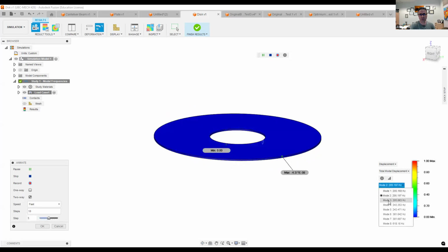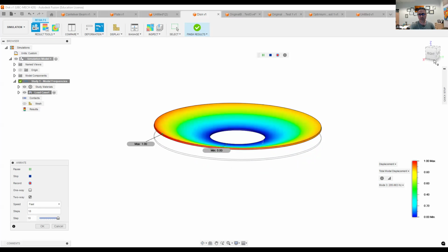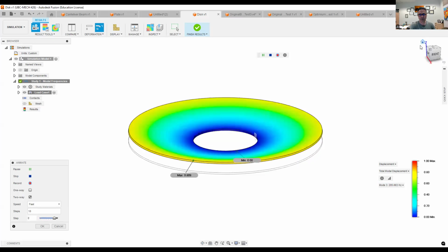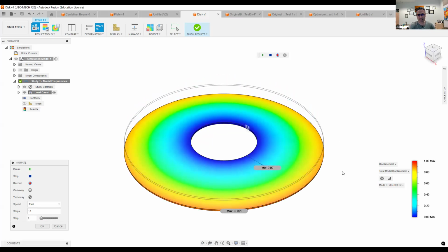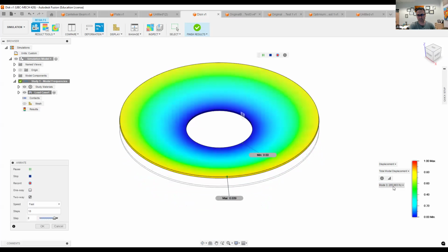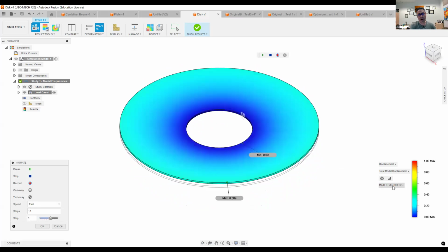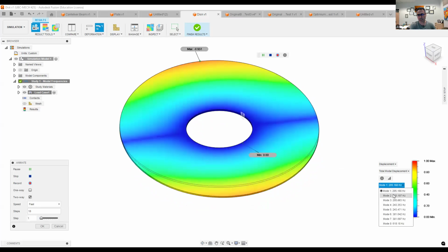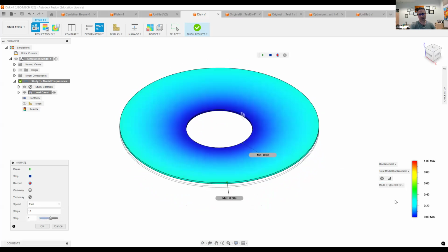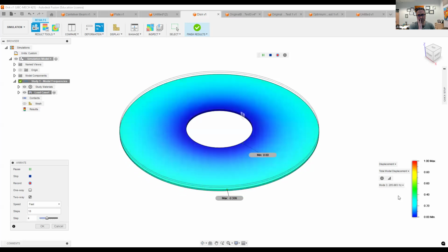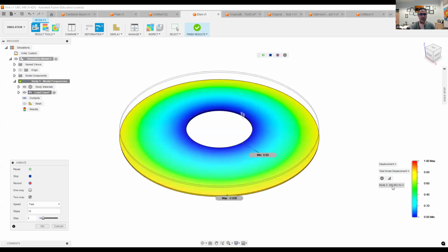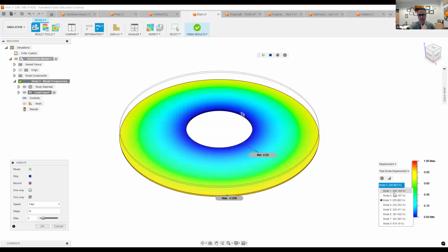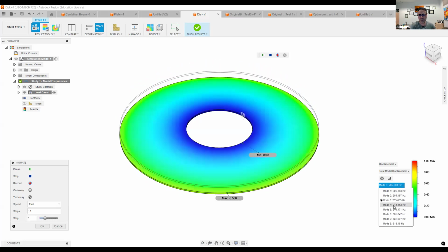Let's take a look at the third mode. Third mode is, if I look at the side, it gets a shape like a mushroom, concave, convex, and it has a frequency, interestingly, of 205 hertz. So the first, second, and third modes all have the same frequency, which happens in this case, but necessarily it doesn't have to be that way. For 1 and 2, yes, because they are just similar modes perpendicular to each other because of the symmetric shape.